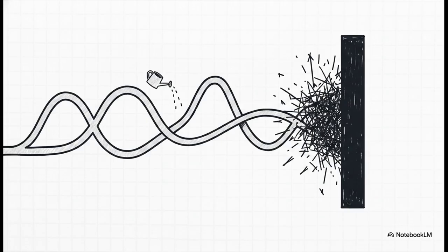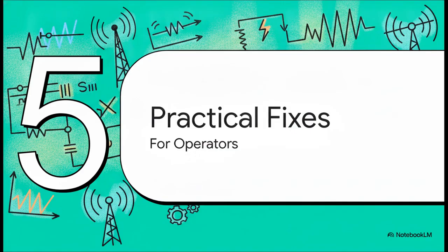To counter this, SDR manufacturers often use a technique called dither. Adding dither essentially means injecting low-level random noise directly into the signal. Take a second to appreciate the irony there, adding noise to fix a noise problem. But it actually smooths out the quantization errors, allowing the SDR to operate smoothly, even though it is fundamentally different from traditional analog overload. Section 5.